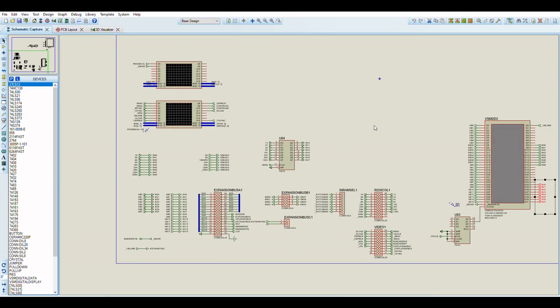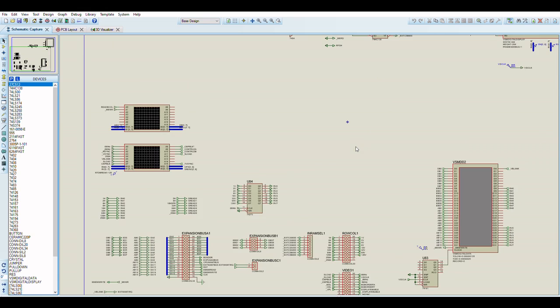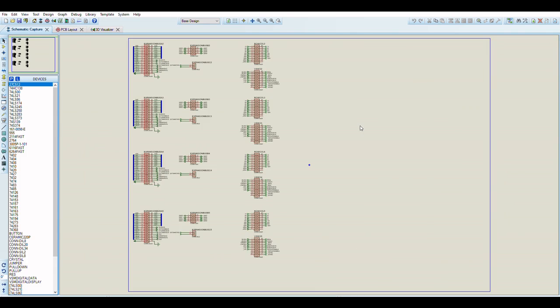It basically allowed me to remove any potential for clock ripple, because the inputs here were potentially rippling around a little bit from the clocks, because it actually uses clocked 4-bit counters to generate the horizontal and vertical pixel clocks, and we'll see that on the other sheets. So sheet 2 and page 2 on the PDF.